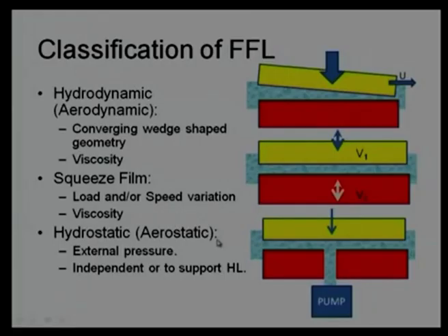The last one is the hydrostatic. You see that we are supplying liquid with pressure. So, there is a pump which needs to supply pressure to levitate this yellow block. The yellow block is carrying the load, right. As I mentioned, it will be a costly affair because using a pump to lubricate requires energy. There will be consumption of energy, as well as the initial cost of the pump and maintenance cost of the pump. That is why it is the least preferred compared to squeeze film action and the hydrodynamic action.